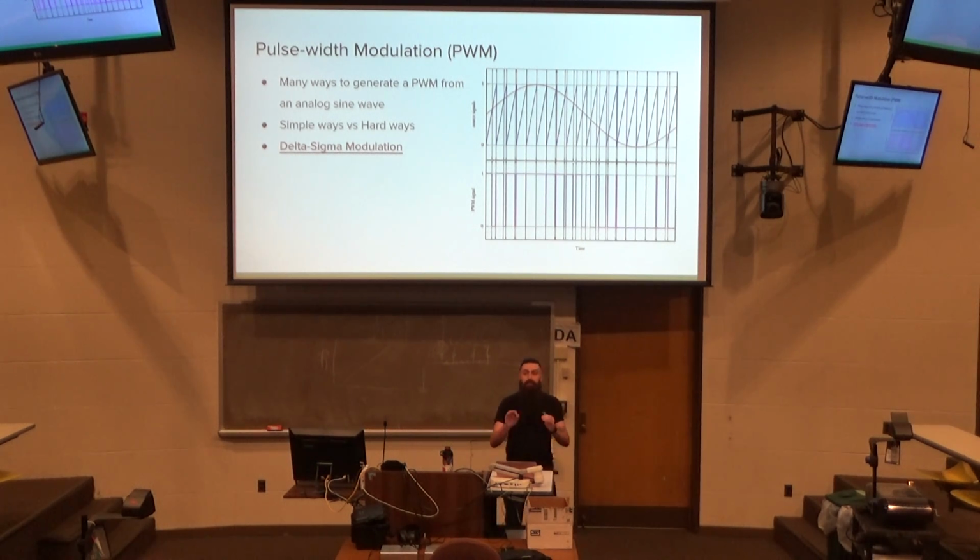Right now, we're talking about the digital version of this with a very set line level of 2 volts. So the 1 is at 2 volts all the time. We can always assume that. We're considering it to be digital. Now it's just zeros and ones like we talked about before. Now we're looking at the simplest way, or one of the simplest ways, to take a sine wave and get this pulse width modulation. If you have a sine wave, you can convert it to pulse width modulation by applying a sawtooth wave over the analog wave.